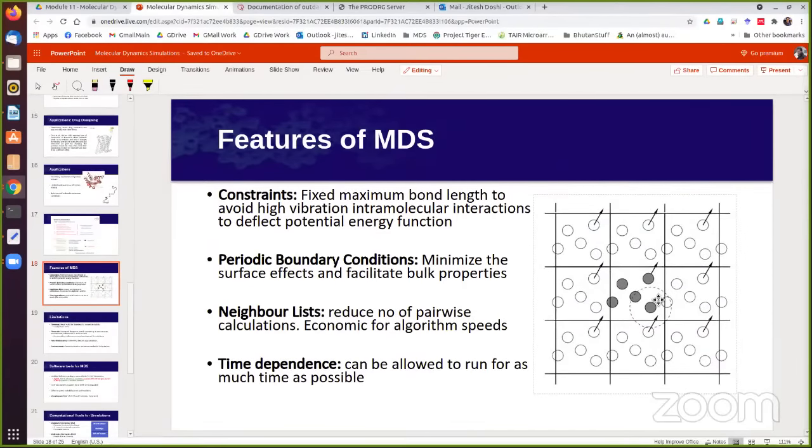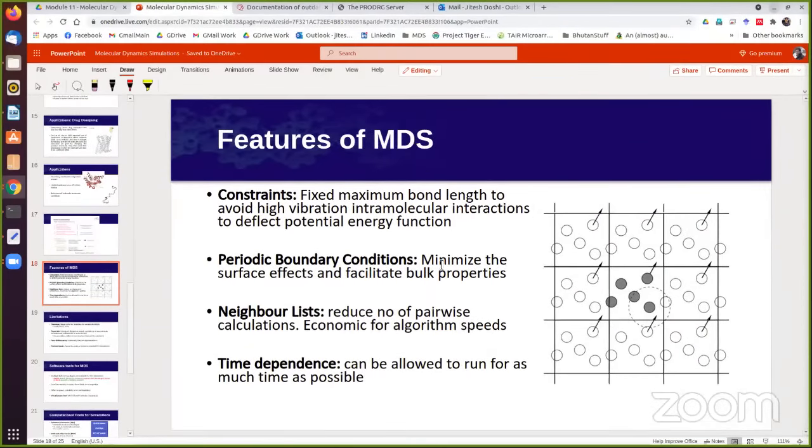Now, if the distance between your protein and another image of the protein is very small, then we are going to unnecessarily compute the interactions between those proteins as well, which we don't want. So keeping the distance safe enough, around 0.7 nanometers or 1, will make sure that at least 1.4 nanometers, if it is 0.7, double the distance, will be kept between the proteins. So between them, the interactions will not be computed. Our requirement is to get the interactions within the given primary box only. So we don't want the cross boundary interactions. That's why the box size can be kept in this way.